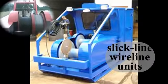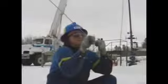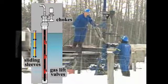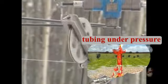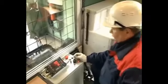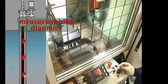The slickline wireline units. These workover units consist of a single strand wire that is used for routine maintenance of gas lift valves, chokes, sliding sleeves, and for cutting paraffin accumulation in the tubing. Here is an illustration of a slickline that is run during tubing under pressure using a lubricator. This procedure is used to measure the tubing diameters to help better gauge corrosion or deposits.